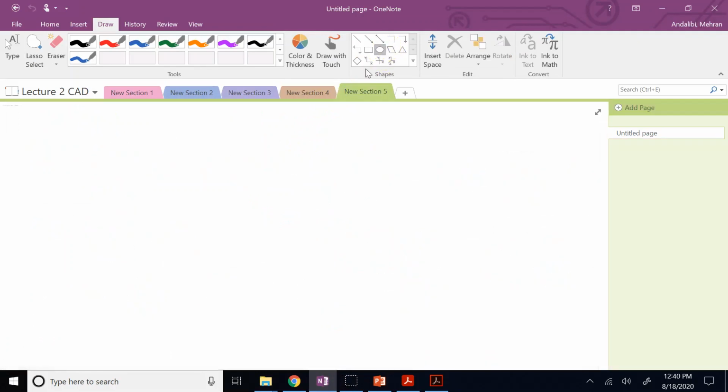So basically what I mean is you should not have something like this, that this is a circle and then the axis of symmetry, they cut something like this. So you have a long one, a short one, a long one, a short one, a long one. And then here you have a short one, a long one, a short one, a long one. So this is wrong. Or if, on the other hand, you can do this, use the long one. This is also wrong too. Only the small ones should cross each other at the center. You have to have a small cross at the center.